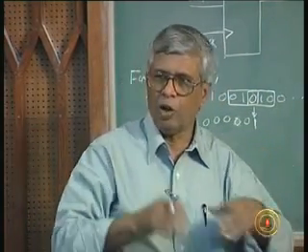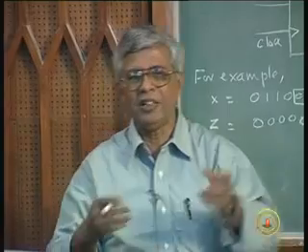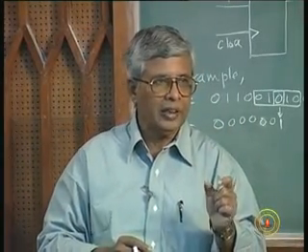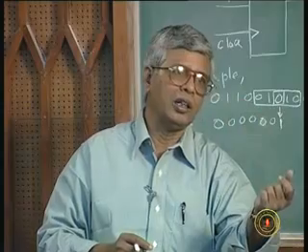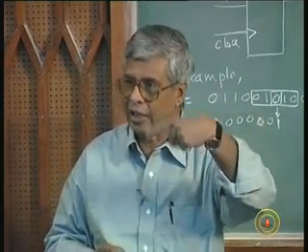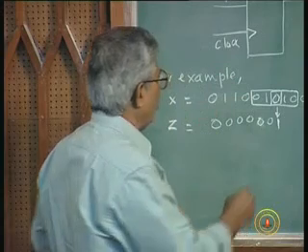So let us now assume overlapping patterns also should be detected. Whenever there is a 0, 1, 0, whether or not a separate pattern, even if it is a part of another detected pattern 101, I should still be able to detect it. If that is the answer, then I should put a 1 here again.